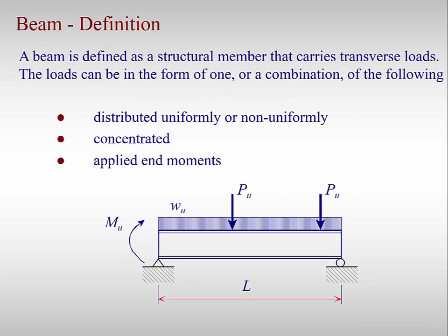Whereas before, when we studied tension members and compression members, they were loaded axially, beams are designed to carry transverse loads. The loading can be concentrated, distributed, either uniformly or non-uniformly, and also have applied end moments, which result in bending along the length of the beam.